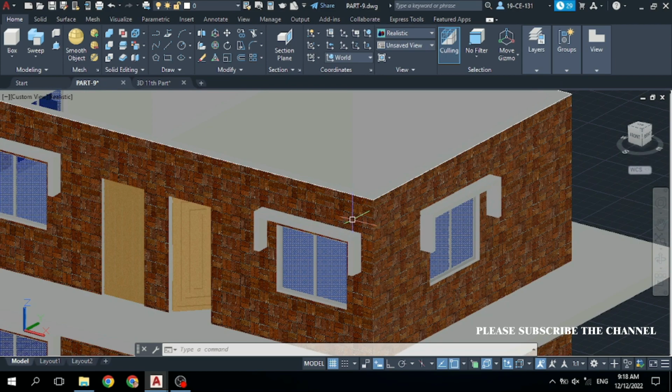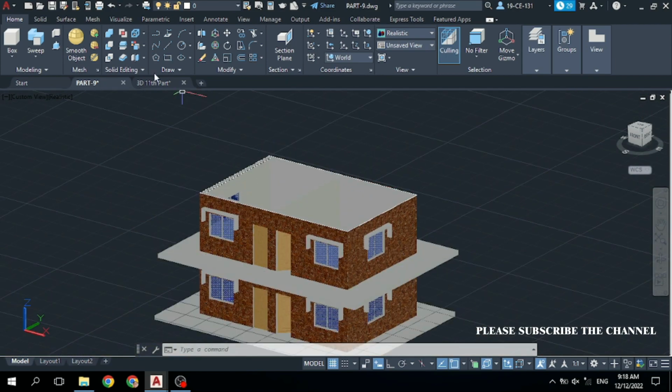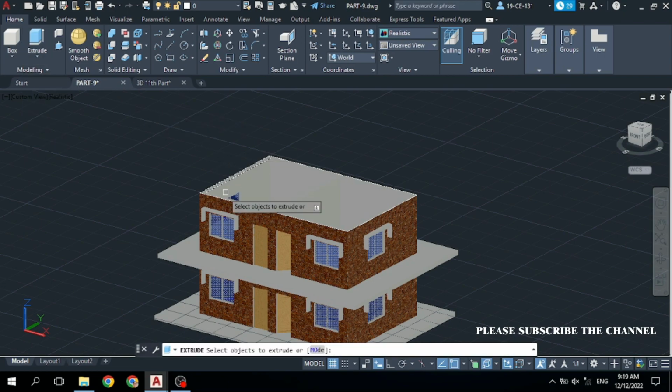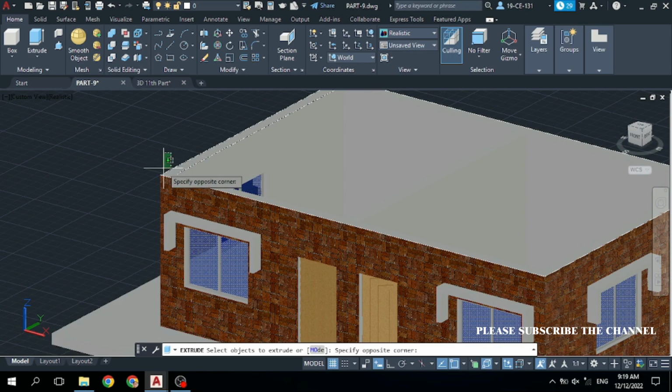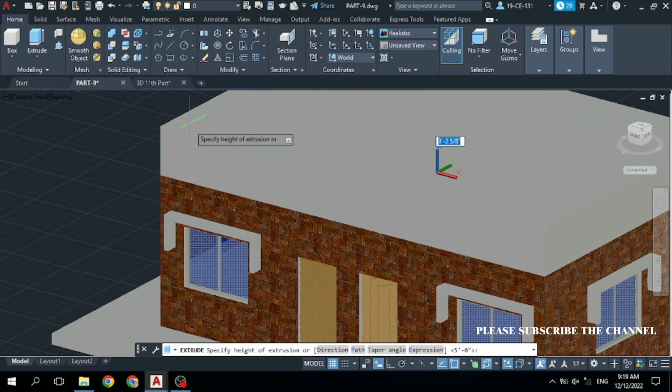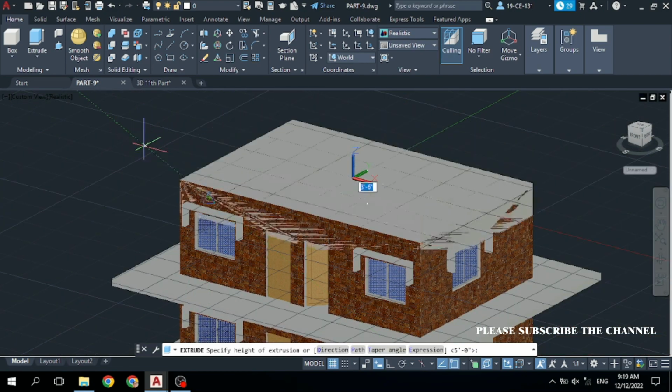After that, click on this extrude command and select this rectangle, and then right click and go upward and type 9-inch distance.